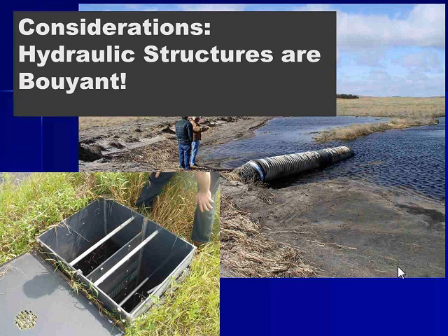Don't forget that hydraulic structures are buoyant, and especially in a wetland landscape where our objective is to increase that saturated surface or saturated condition up to the surface. Buoyant forces are especially strong. The large picture on the right with that broken tube, that tube was submerged and flowing partially full at the time it failed. And because it was flowing partially full under inlet control, there was enough buoyancy to float it to the surface. The lower right is a typical agri-drain stop log structure, and those structures are subject to buoyant forces that is largely unrecognized.